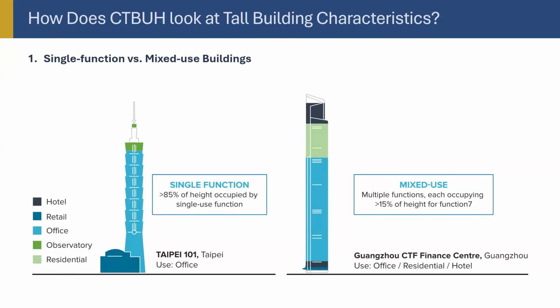And what that means for structural engineering is that you have different loadings coming up. For each type, the loads are different. Performance criteria is different. The grid is different. The layout is different. Parking is another one. So sometimes what happens is that the columns are coming down, and then suddenly there is a shopping center with a movie theater here. You cannot have the column in the center of the movie theater. So all the columns have to stop at that level and then start again. So you have this major structural discontinuity that you have to manage.